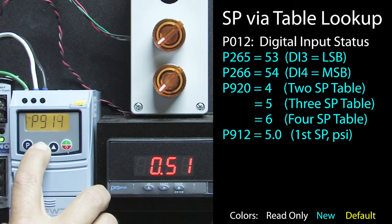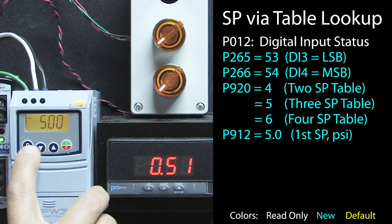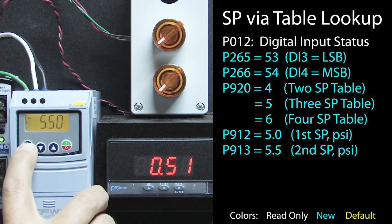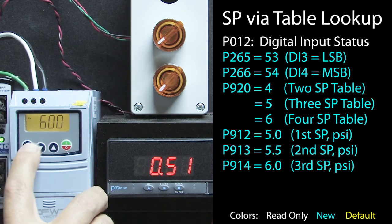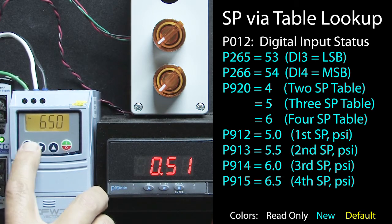Now we'll go to parameter 912 to enter the first set point. How about we make that 5 psi? Parameter 913 is the second value. We'll make that 5.5 psi. Parameter 914 is the third value, so we'll make that our usual 6 psi. And parameter 915 is the fourth value, so we'll set that to 6.5 psi.